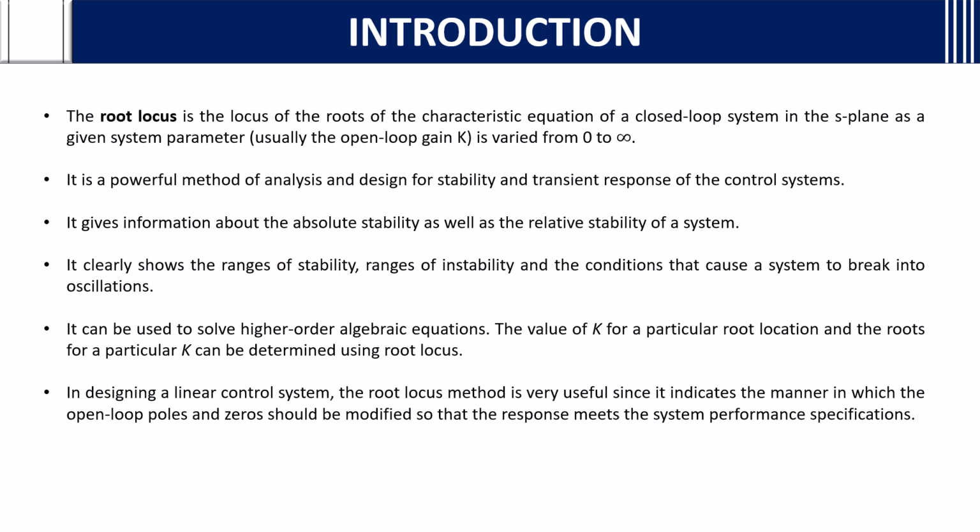Introduction. The root locus is the locus of the roots of the characteristic equation of a closed loop system in the S-plane as a given system parameter, usually the open loop gain, is varied from 0 to infinity. Root locus means a locus of roots of the characteristic equation of a closed loop system in the S-plane.